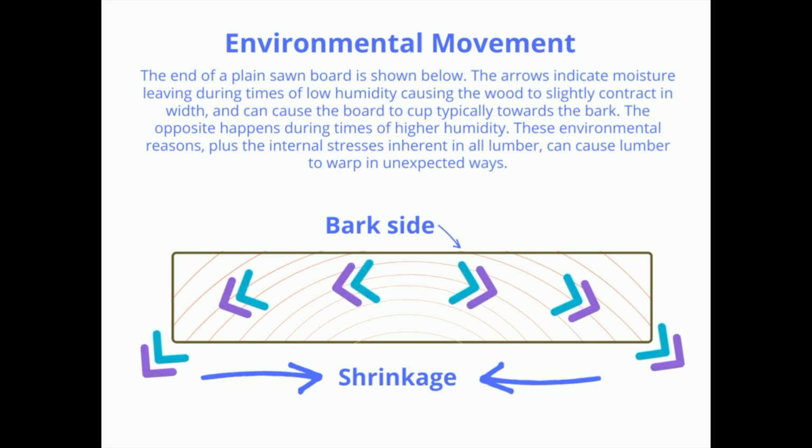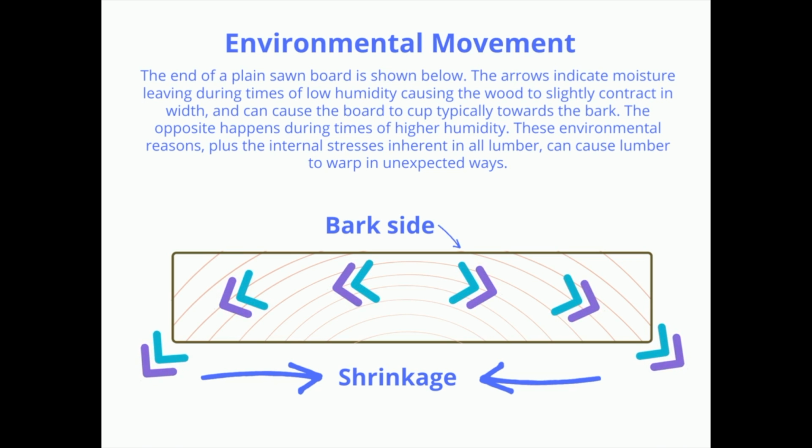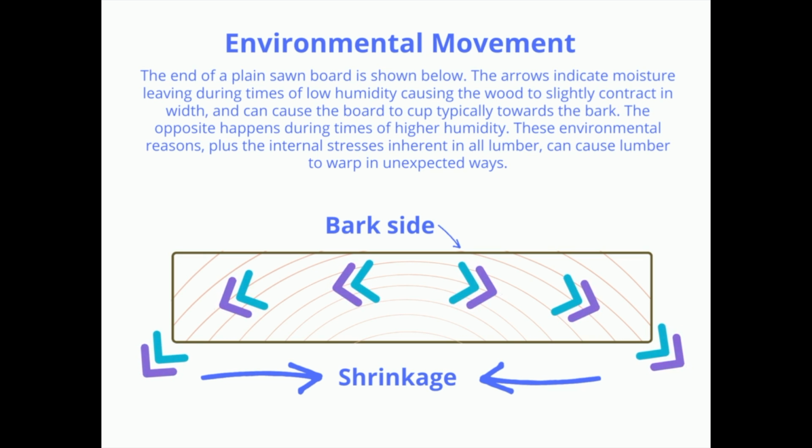But wood movement does have some hard and fast rules. For example, wood expands in the summer with higher humidity and contracts in winter with lower humidity. I think most everyone can understand these environmental causes of wood movement. This absorbing or releasing of moisture, while minimal in a home with HVAC, will continue as the wood cells try to reach EMC, or equilibrium moisture content, with the surrounding air.